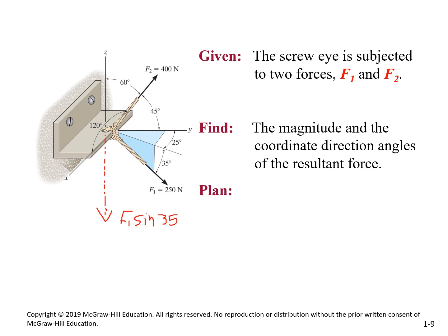And then I will create another force here. I'm trying to analyze F1. I'm going to call this F prime, and this F1 prime is going to be F1 cosine 35, correct? I don't need this, that's gone. Now, this one here needs to be projected on the x and y. I have with the y-axis 25. So I can say that this here is F prime 1 cosine 25, and that equals F1 cosine 35 multiplied by cosine 25.